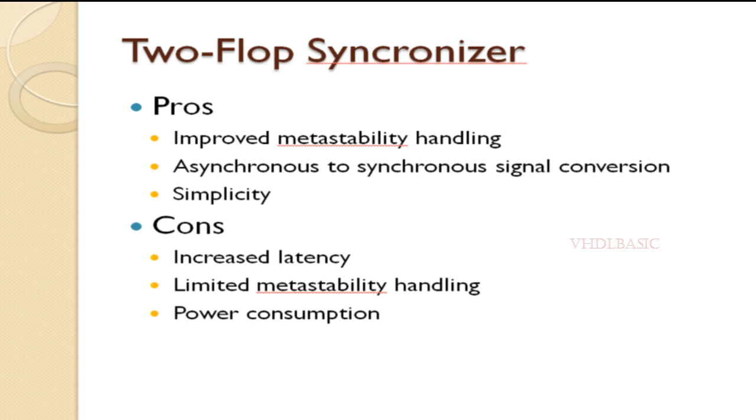Here are some pros and cons of using a two flip-flop synchronizer. Pros: improved metastability handling. The two flip-flop synchronizer reduces the probability of metastability compared to the single flip-flop synchronizer. By capturing the input signal in consecutive clock cycles, the chances of capturing metastability are slightly reduced, significantly reduced actually.